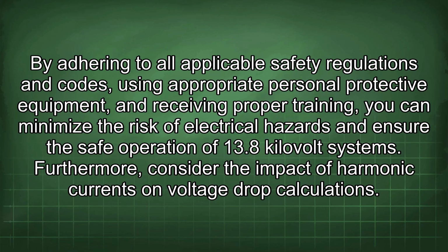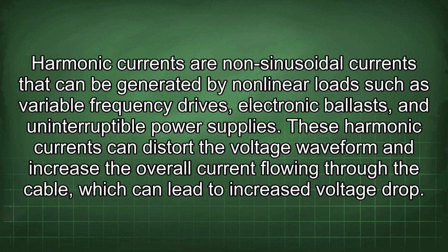Furthermore, consider the impact of harmonic currents on voltage drop calculations. Harmonic currents are non-sinusoidal currents that can be generated by nonlinear loads such as variable frequency drives, electronic ballasts, and uninterruptible power supplies. These harmonic currents can distort the voltage waveform and increase the overall current flowing through the cable, which can lead to increased voltage drop.